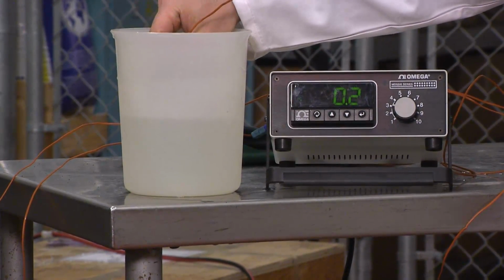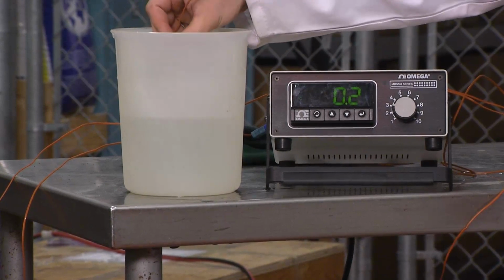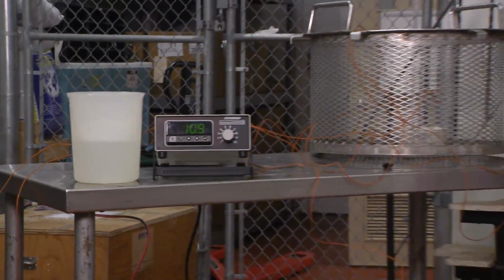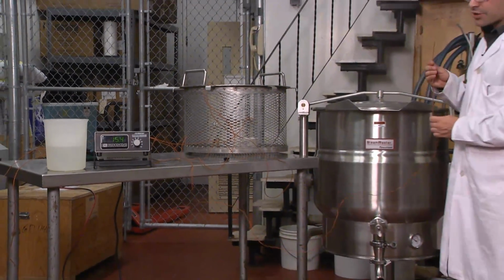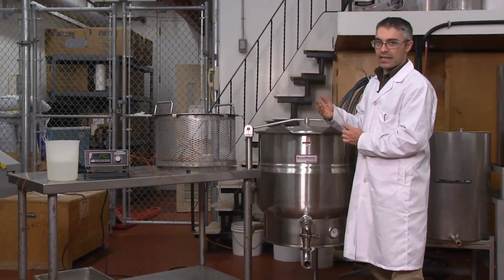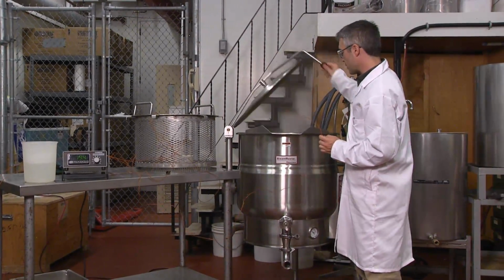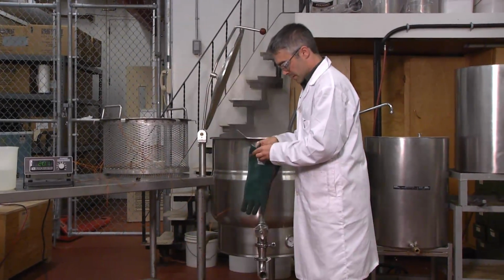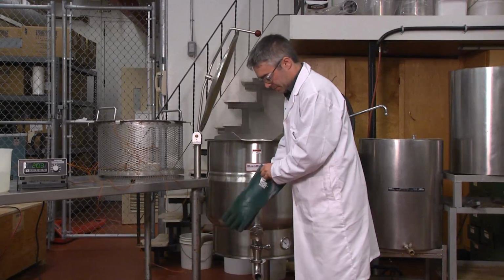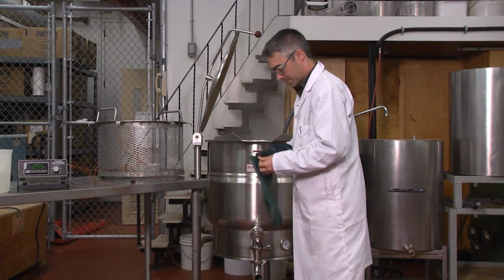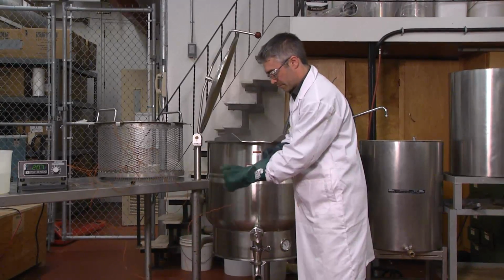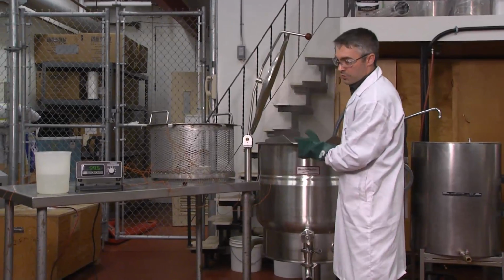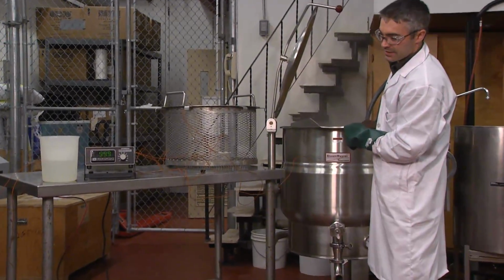Once you have the absolute 0, or the 0 degrees Celsius temperature for each probe, you'll also be using water at 100 degrees Celsius to perform the high point of the calibration. In this case, we have our boiling water. We will don our thermally protective gloves. And after submersing the thermocouple into the water, we should be reading very close to 100 degrees Celsius.